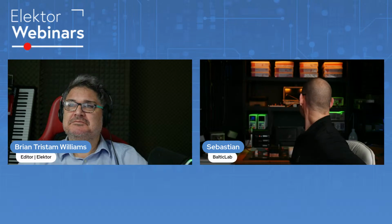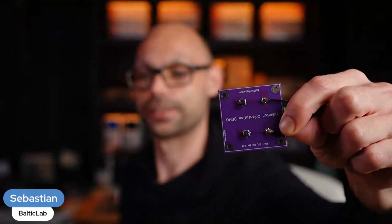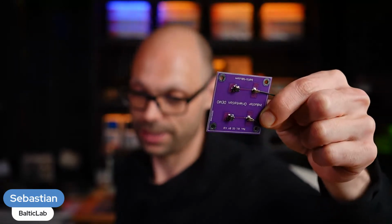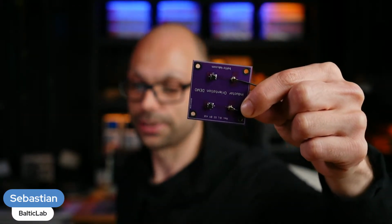Actually, the test PCB is still sitting behind me. All right, let's see if we can get that focused. The light is on. Yeah, we can kind of see it. There are two inductors on there, and the only difference between the two is their orientation. If you apply the same signal to both of them, the spectrum is actually entirely different.